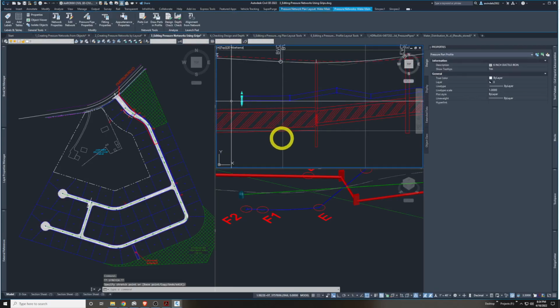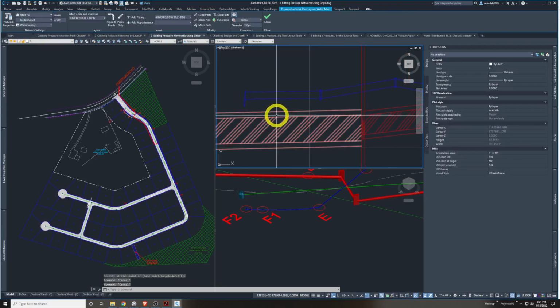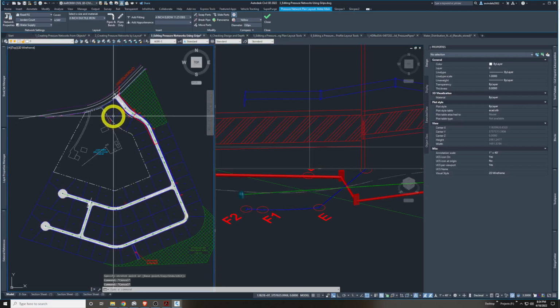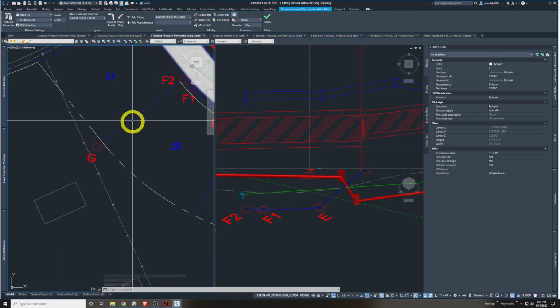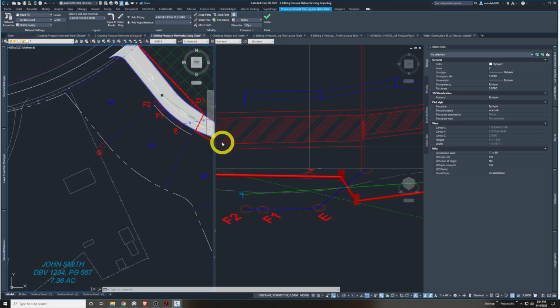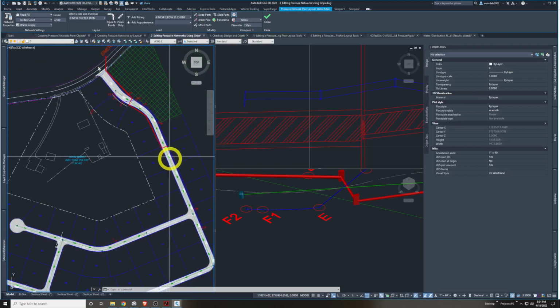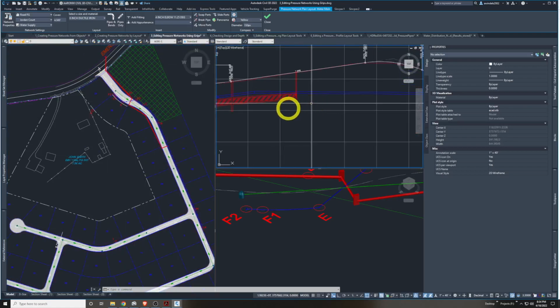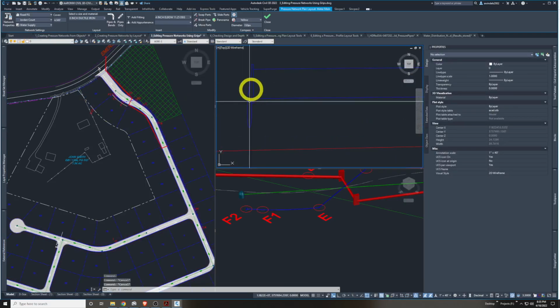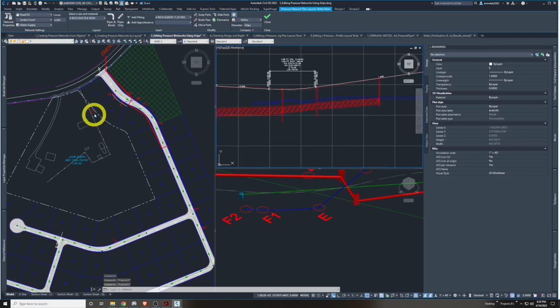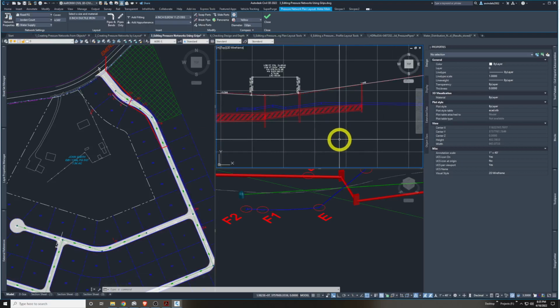This essentially is going to look kind of weird in this view because this area of the pipe network runs perpendicular to our alignment Jordan Court. So most things are going to show really good if they run somewhat parallel with our alignment Jordan Court along here. Like most of our pipe network, it sort of does, but if it runs perpendicular like this, you're going to get interesting looking things on this profile view. So you maybe want a profile view running parallel to this direction to better show that. So that's pretty critical to try to get your profile views set up so they're favorable to be analyzed.